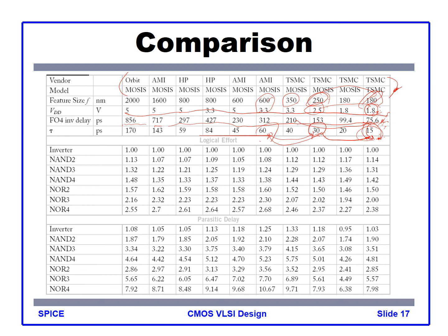For the logical effort, we specify that the inverter logical effort is 1. Among the different logic gates, the NAND 2 is always the second best, close to the inverter. The NAND 2 is fast in logical effort.